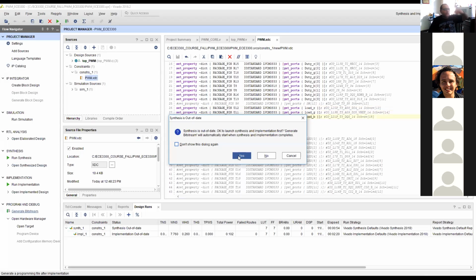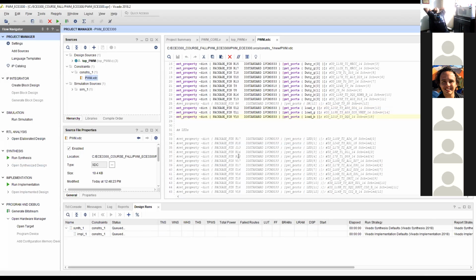So this is one of the disadvantages of FPGA, that every time you have to run synthesis, right? But then there is something in hardware description languages in general called overlay architecture. You will build a wide range of reconfigurable IP, and from there the software will be changing it momentarily, at runtime, and you don't need to run synthesis every time. But this is beyond the scope of the 3300. I don't want to overwhelm you with a lot of information.